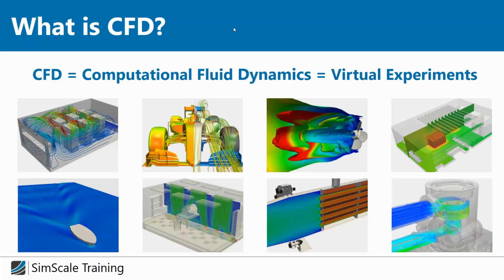For example, a lot of our consumers are using our CFD capabilities to simulate cooling processes inside of electronic devices. And this simulation here shows such a result. If you really take a look at it, you can see this is basically the inner domain, the inner volume of an electronic case. And here you can see the heat sink. Here are some openings, some bonnets, where the hot air can leave the system. Here are some inlet ducts, and this kind of simulation helps to predict and optimize the cooling effect of the flow.